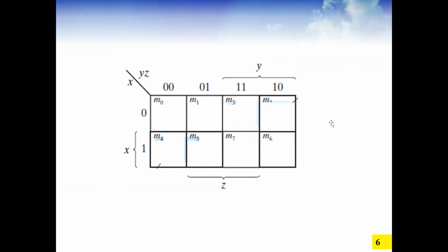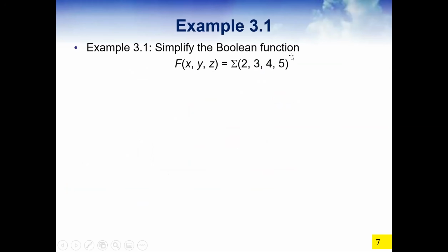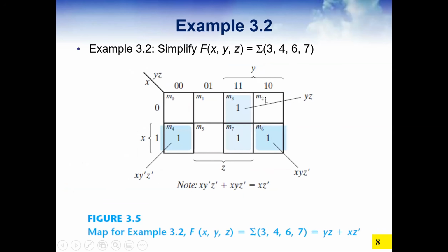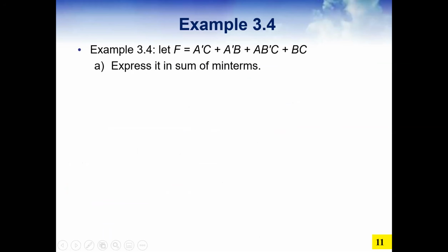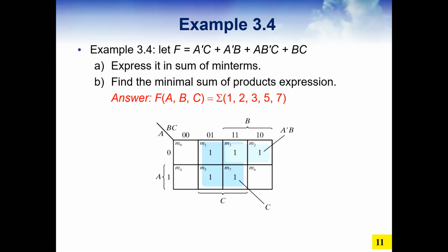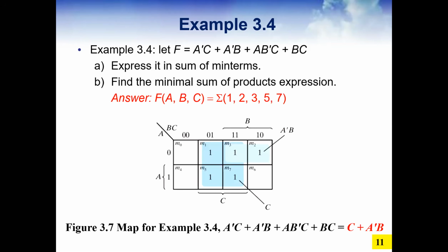Now, okay, I'll be moving on. So these are some more solutions which I have already covered. Now, for example, see this one. This question may also come like that. Here you can see this is a standard form. Basically, we need to first convert this into canonical form, bringing in all the literals. After bringing all the literals, we will find the minterms. Then we can just place them and simplify. So the examples in the slide are very simple.